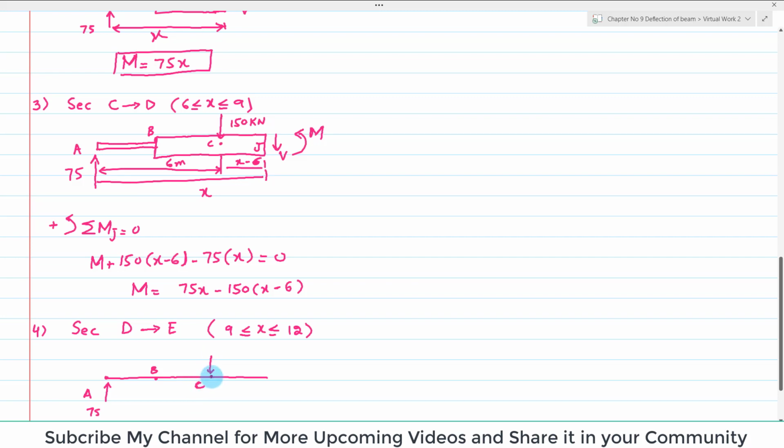150 kilonewton applied, and let this be point D, and point E will be on the right side. But here if you cut the beam, there will be a shear force and bending moment. So let the total distance be x here. So this is x, and this distance is 6 meter. So definitely this distance will be x minus 6, and it is the same like this.